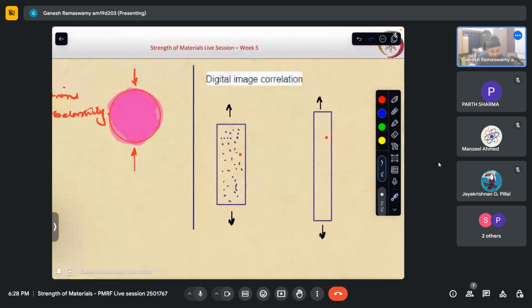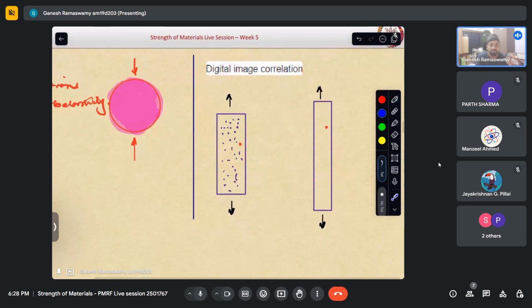Once we get displacements, we saw in the previous session that we can maybe fit a curve, get a displacement field, take its derivative. The gradient of the displacement field will give us strains. From strains, using constitutive relations, we will go to stresses, integrated back to the force which we applied. And we know everything about the problem. This I have explained in the context of a simple tension test.